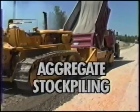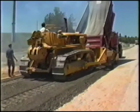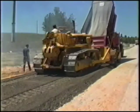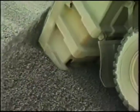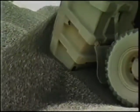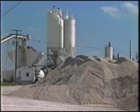Aggregate materials have many uses in highway construction. Dense graded aggregate is used as a base material to provide stability, strength, and drainage. Open graded aggregate, sometimes called clean stone, is the major component of asphalt and concrete mixtures. Clean, well-graded sand is also an important aggregate material used in the production of these materials.